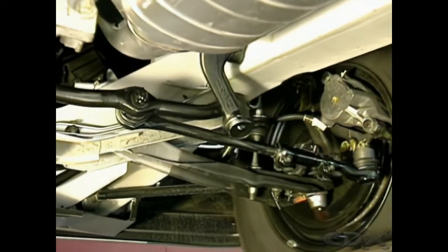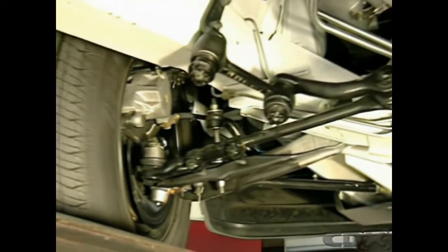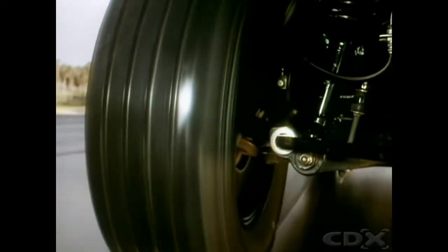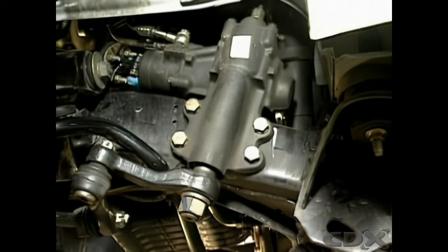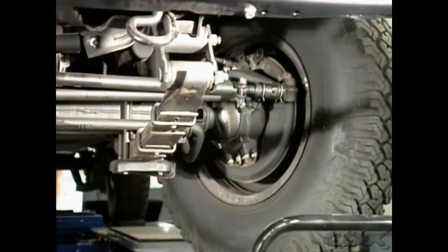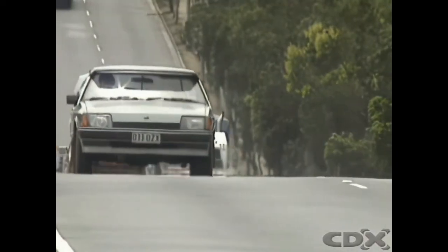The steering linkage is a combination of rods and arms that transmit the movement of the steering gear to the front wheels. It must transmit this movement to the front wheels, while still allowing for up and down movement they may make while the vehicle is in motion. The type of steering mechanism and the number of linkages depends on the type of steering box, its location, and the type of suspension on the vehicle.